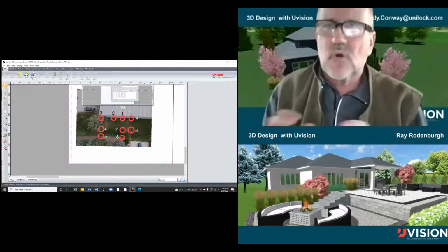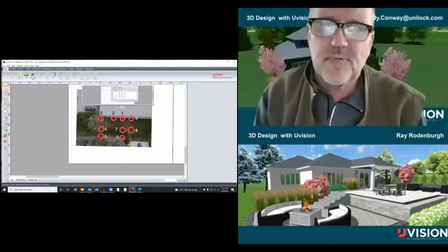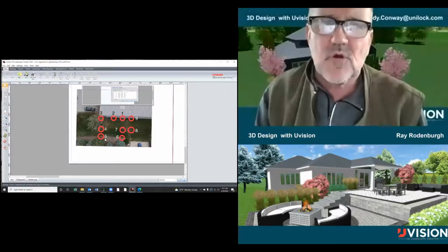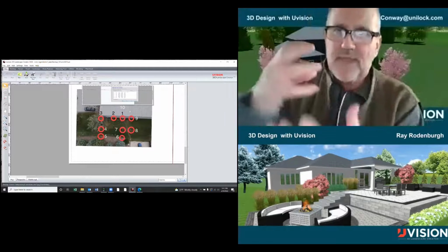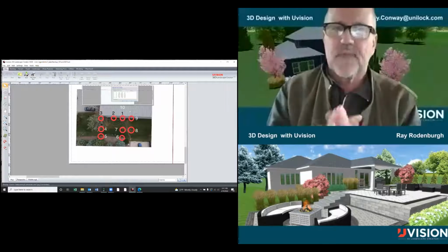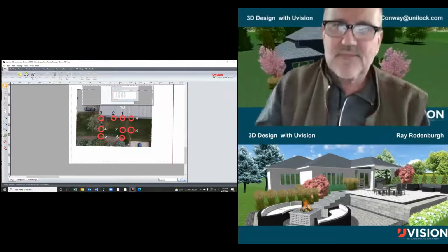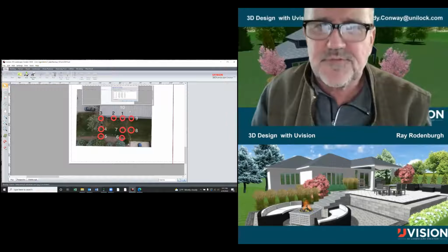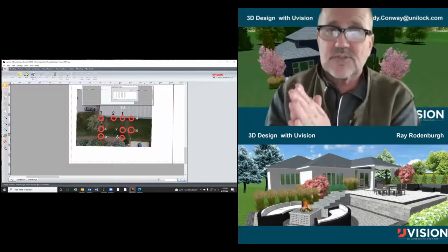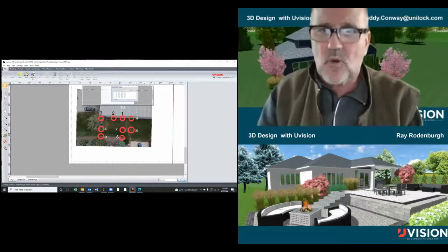And what I do on site is I edit the photograph, and I put big rings around the cones. So when I import that in, I import it in as a survey, as an overlay. I can literally get the distance. I know the door was 3 feet wide. Resize using known distance, 3 feet wide.